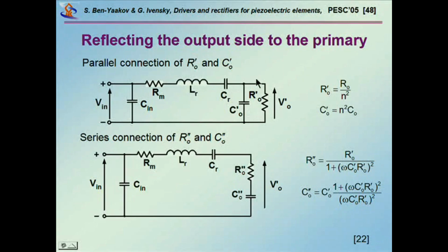When you go up, then this capacitor becomes important, and you have a different resonant frequency, and you can find there another optimum or maximum for the power for the larger resistance. So there are actually two modes of operation: one is this resonance, and the other includes the capacitor, this and this in series.